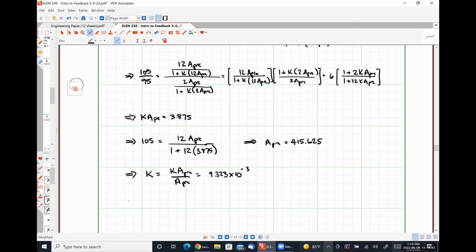Absolutely, right? But what we wind up doing is using effectively what are called voltage divider networks. I mean, you guys are all familiar with that, where we effectively just have two resistors in series forming our feedback system. The reason why that works is because if we have two resistors in a network that are made out of the same material, they're going to both experience the same change in resistance due to temperature variations.